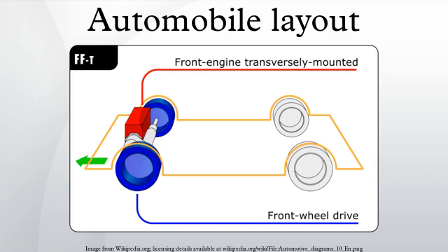The direct connection between engine and transaxle reduces the mass and mechanical inertia of the drivetrain compared to a rear-wheel drive vehicle with a similar engine and transmission, allowing greater fuel economy. In front-wheel drive cars the mass of the drivetrain is placed over the driven wheels and thus moves the center of gravity farther forward than a comparable rear-wheel drive layout, improving traction and directional stability on wet, snowy, or icy surfaces.